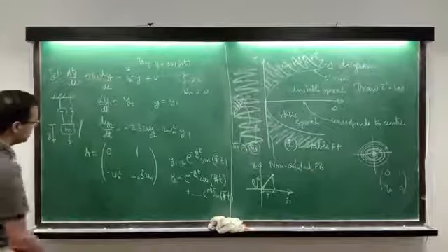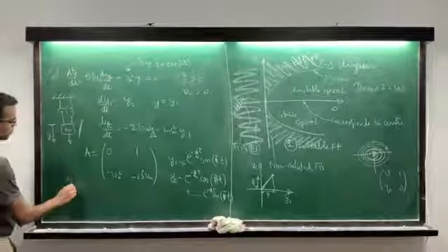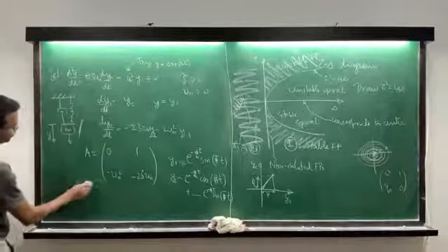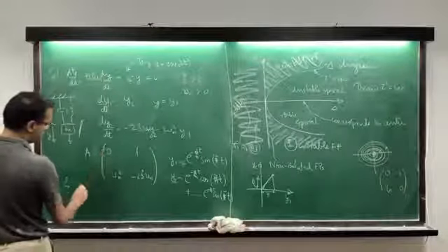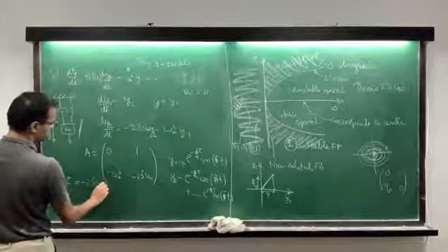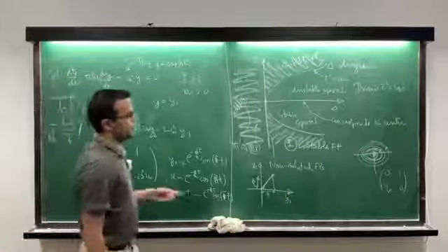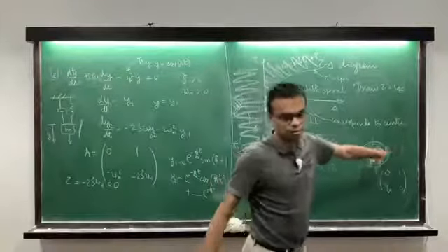What are the lambdas here? Well, let's get the tau. The tau is the trace, it's minus 2 xi omega n, and this is negative. So you have negative here. This is a stable spiral.